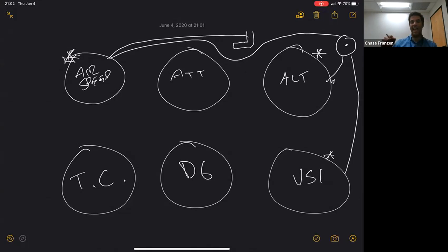So it knows that as I descend rapidly, the aneroid wafers are changing in size, but there's this small orifice that's allowing the air to escape, and that's what the instrument is measuring. And it's important to note that the VSI, because of all of these linkages and the aneroid wafer, and because you're literally measuring this calibrated leak, lags. It's not a perfect indication. If I nose over the plane and start descending at 1,500 feet a minute, the VSI is going to take 5 to 10 seconds to catch up. It's probably my least favorite instrument of the six-pack.